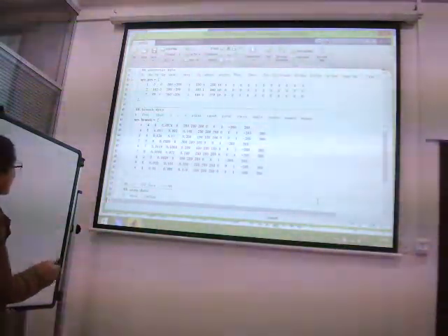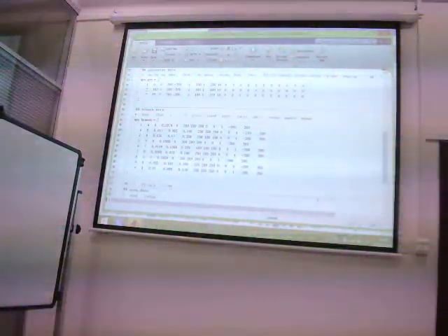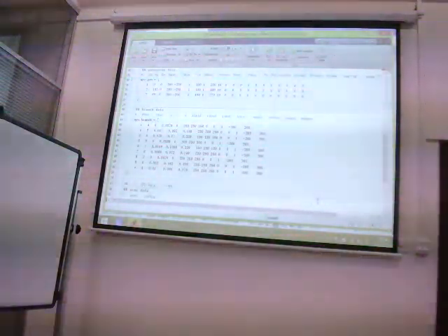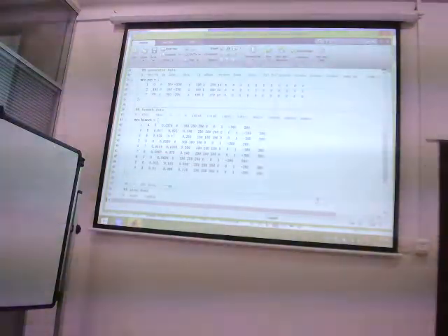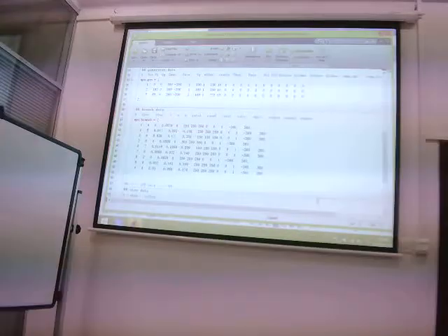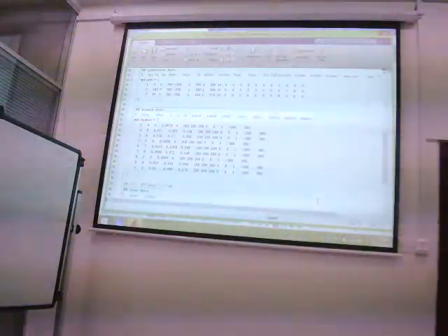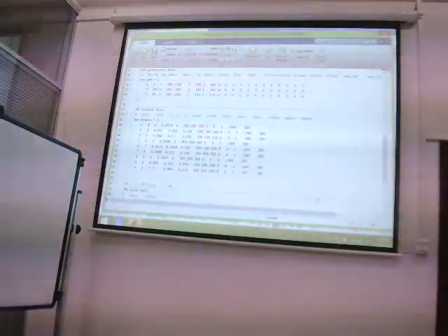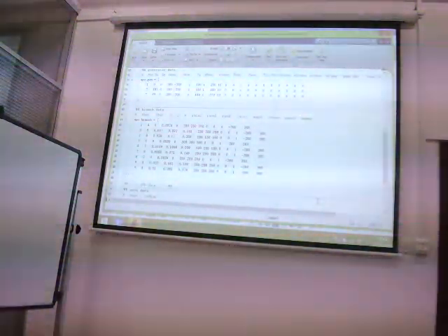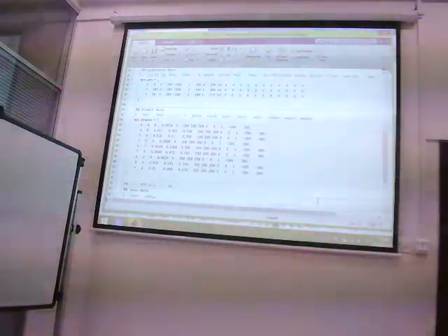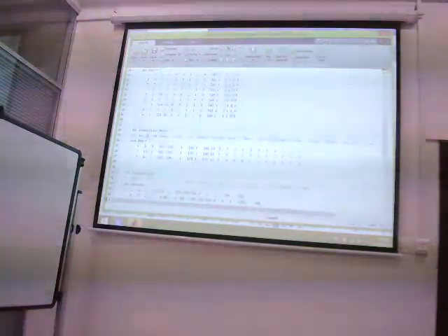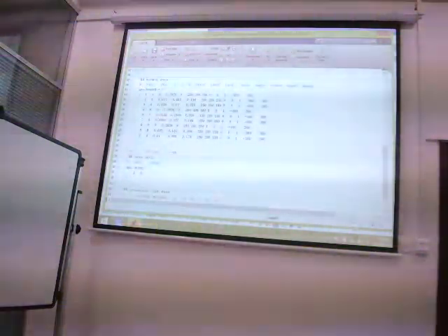For the branch data, we have the resistance, the reactance, and the susceptance, R, X and B. You can see them in the third, fourth, and fifth columns of this data. Also, we have the ratio and the angle information. Now, this is the basic information for our system. You have to put in the bus data, generator data, and the branch data.